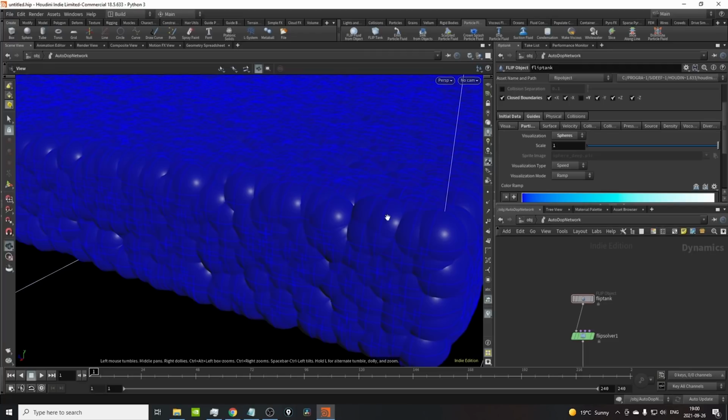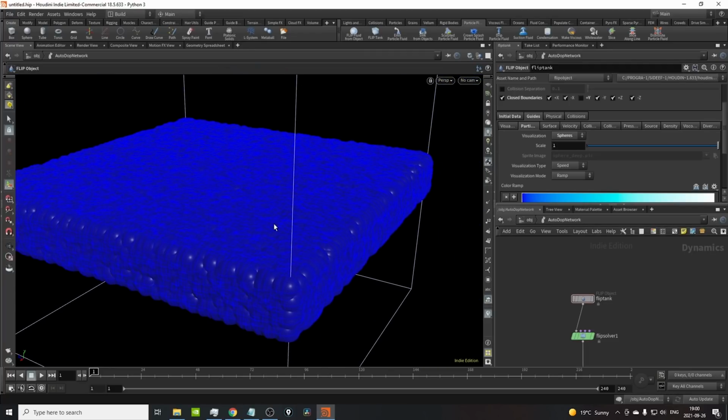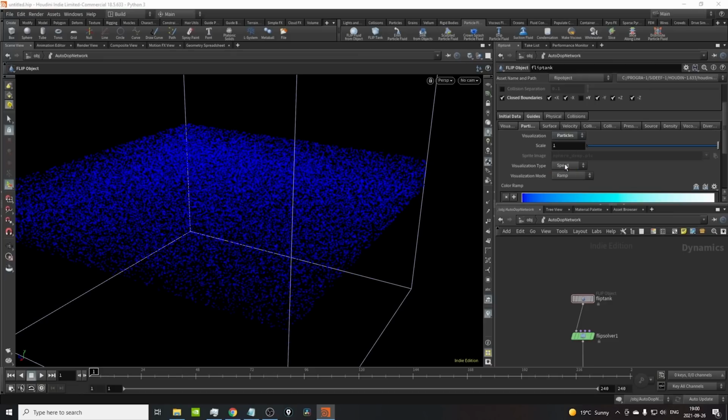It's these big spheres, specular, and they slow down your GPU, they slow down everything, especially once you get to higher resolutions in your simulation. I literally had cases where my whole computer crashed, even though the simulation didn't run yet, just trying to draw the first frame. So visualization, change this to particles, and you can even save this just as the default.